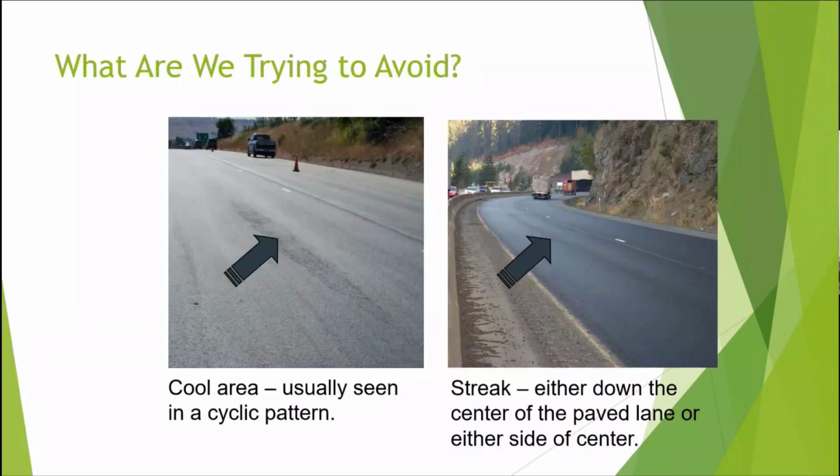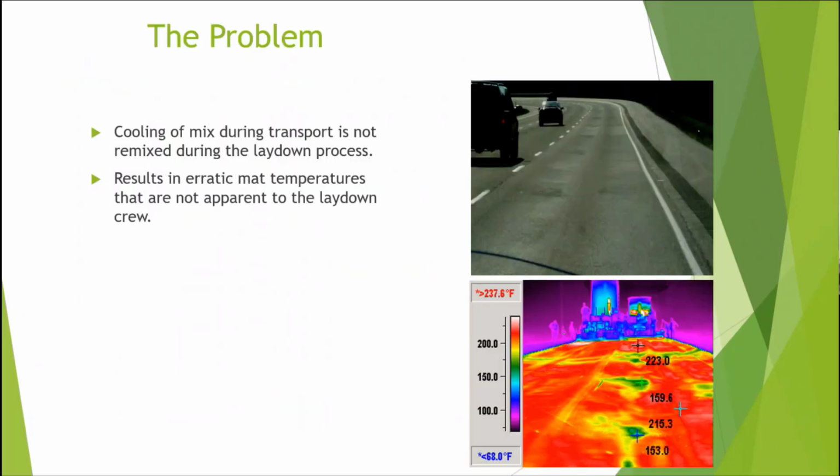And segregation will cause that as well. And here you can see it. That's one thing you're looking for out in the field: I don't want to see strips like that. If I do, I'm getting segregation. Could be a paver feed, could be a mix issue. Now you need to work from the back all the way back to the plant sometimes, to determine how that's happening.